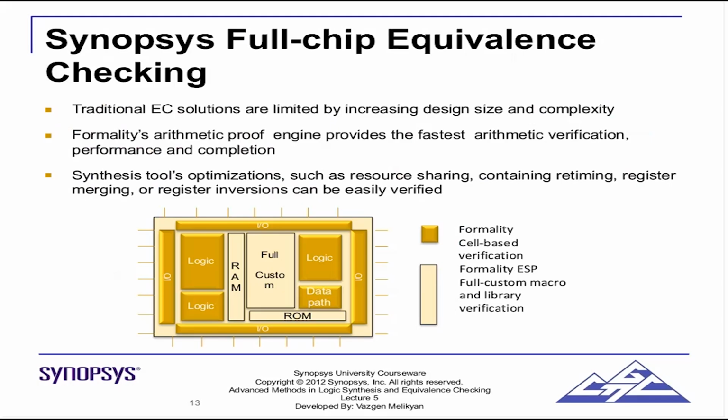Whatever digital design you have, a complete synthesis based design like logic, where logic here means an RTL design that is synthesized. Again, data path is nothing but RTL which has a lot of, let's say, adders and multipliers. Only the full custom part, that is the RAM, ROM, and any other full custom logic, can be verified by ESP, Formality ESP. As I told you before, it compares the behavioral model against the transistor level netlist.